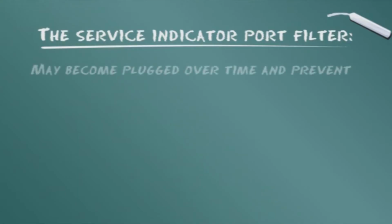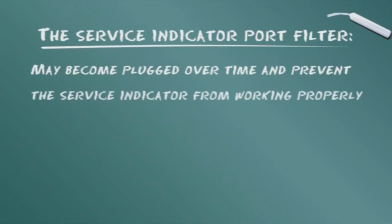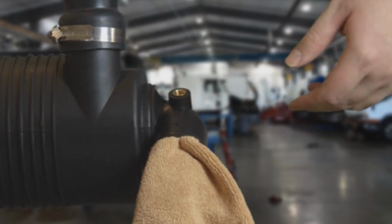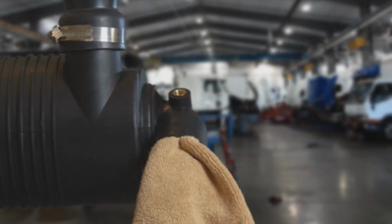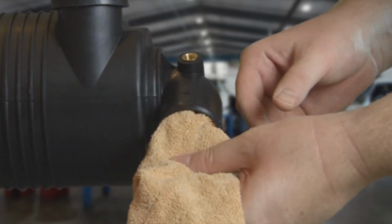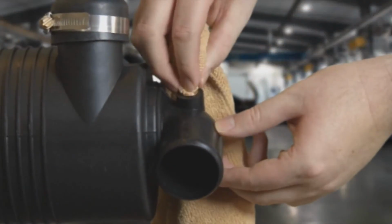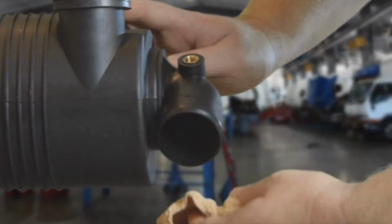This filter may become plugged over time and prevent the service indicator from working properly. To correct, use a 1/8 inch or 3 mm drill bit to drill out the old filter in the indicator port. Once completed, remove the rag in the outlet tube. Make sure all contaminant is removed from the indicator port and air cleaner outlet tube.